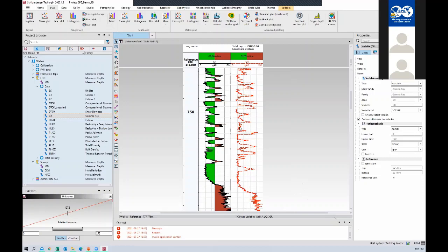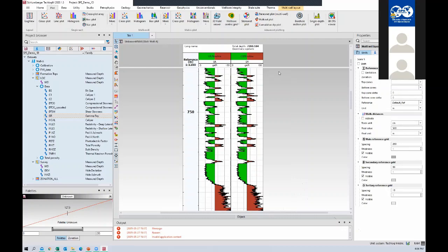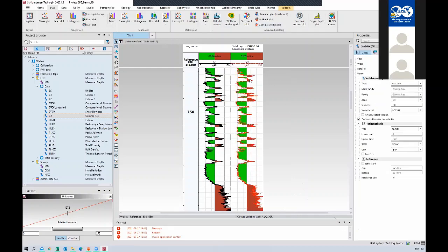You have to match the patterns that you observed in the correct data set. It's important to understand here I'm saying correct data set, right? You need to fix one thing first, that this gamma ray is correct and this is not. Once you know this is correct and this is not, then you can maybe do a block shift, or you can shift area to area, region to region. So that comes under log conditioning.